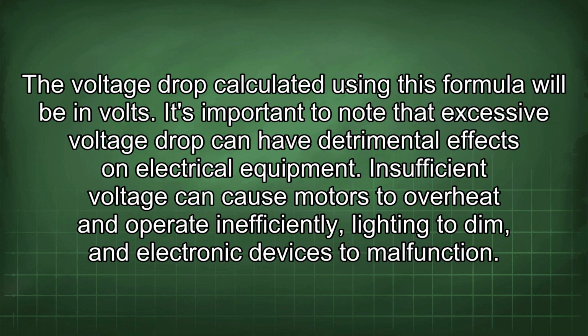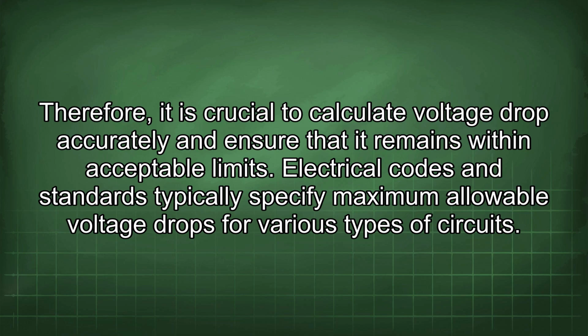It's important to note that excessive voltage drop can have detrimental effects on electrical equipment. Insufficient voltage can cause motors to overheat and operate inefficiently, lighting to dim, and electronic devices to malfunction. Therefore, it is crucial to calculate voltage drop accurately and ensure that it remains within acceptable limits.